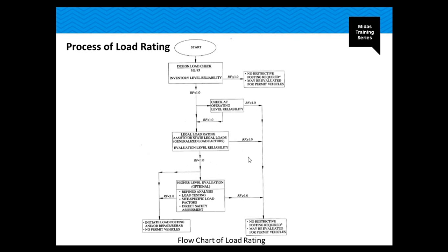If it goes okay with the legal load rating, then it's fine. If it does not, then we need a higher evaluation load rating. We might need the load testing, site-specific load factors, direct safety assessment, refined analysis, and there's where different types of programs come in, such as the Midas Civil and so on as well. You can also perform it for the design load check. It's the one that we're gonna see today.